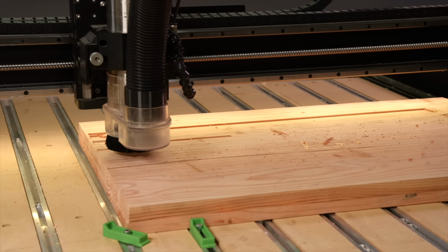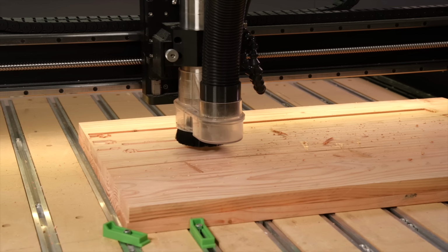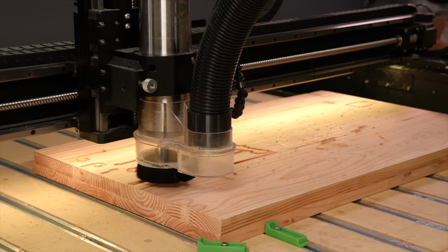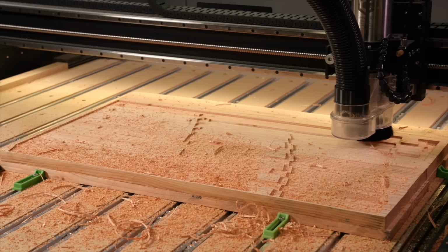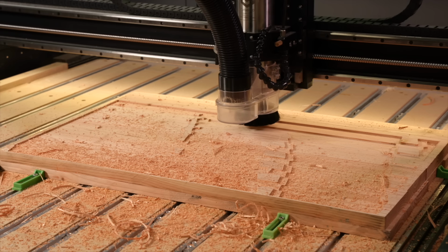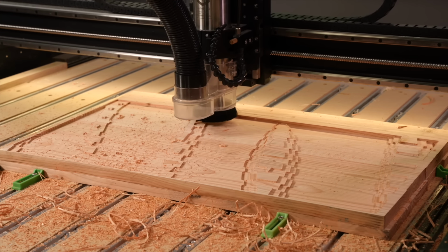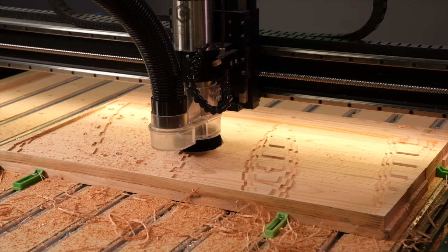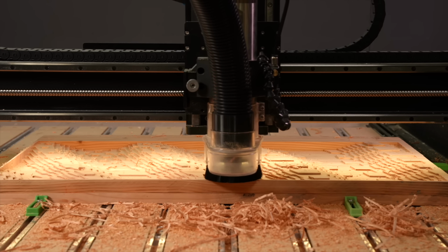Here is the initial roughing phase of the flag machining. This was done with a 1/4" down-cutting flat end mill, and the biggest thing I'm having to contend with here is the fact that the construction-grade lumber that I'm using likes to leave long fibers that clog the dust boot. If I could do this all over again, I might instead try a roughing end mill to disrupt the formation of these strands, and use a larger diameter end mill to get through this material in fewer passes. Or if I didn't have to worry about the budget, I'd make this out of walnut or something. The next thing I'm going to do is run that finishing pass over the stripes.